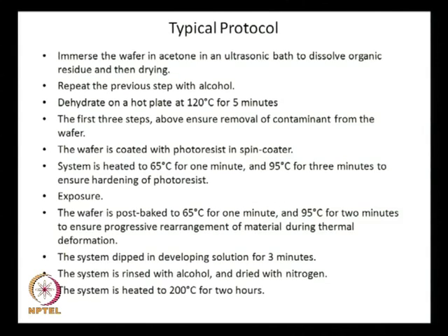So, this is a typical protocol that is followed. I mentioned that at first you have to put a mask aligner and take the exposure. Prior to that, you have to have spin coating done, but I said that particles are not allowed on the substrate surface, because if particles are sitting there on the substrate, that can disturb the spin coating process and the coating will not be uniform, and there would be all kinds of problems coming up.